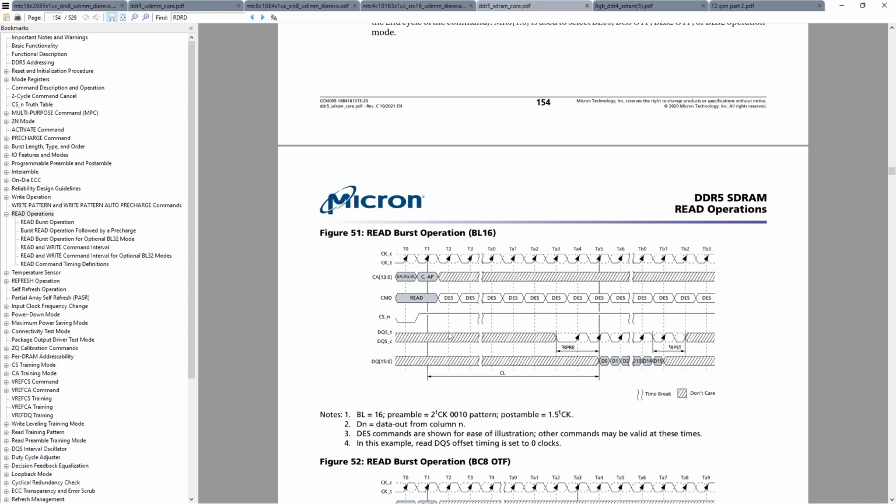So this is how DDR5 memory sticks function: you have the two independent channels. The other benefit is you can send completely independent commands to each of the memory channels, right? So you can be reading on one memory channel while writing on the other memory channel, or you can be reading from address X on one memory channel while reading from address B on the other memory channel.